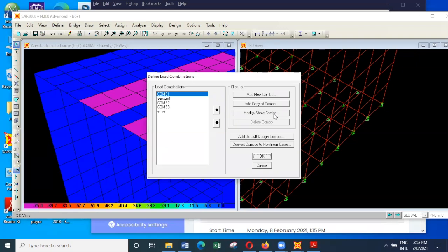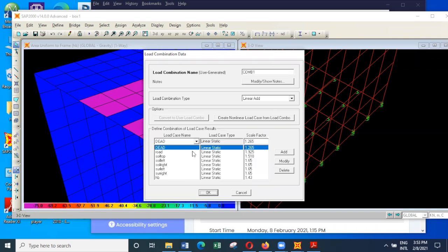here you can see dead load has a factor of 1.15, and we have to multiply it by 1.1. So the dead load has a factor of safety of 1.15, but I told you that we have an additional factor of gamma F3, which is 1.1. So the overall factor will be 1.15 multiplied by 1.1.